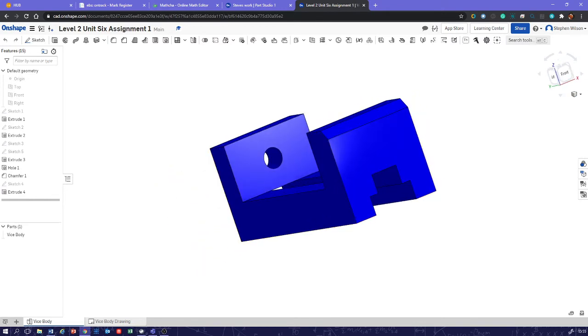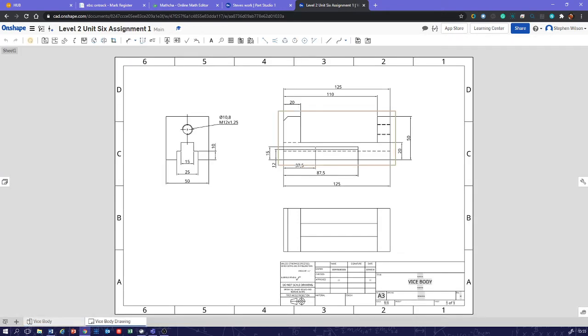So if we flick back to here, that tells us that hidden detail line is at the same place as that line here. So it must be the same height or depth. Oh, that's an odd place to have that dimension. That dimension says it's 20. That's 20 there. I'm going to change that, in fact. I'm going to change that right now, and hopefully, because I'm sharing this with you, that should change the model. There we go. So that's 20. That should change it when you view it as well. So that's 20 from there to there. That means it must be 30 from the top down.